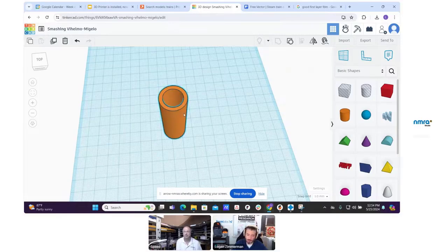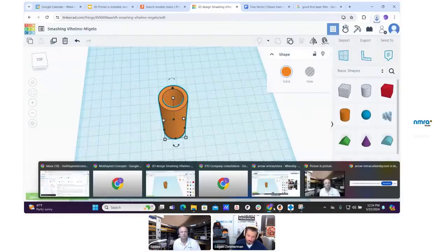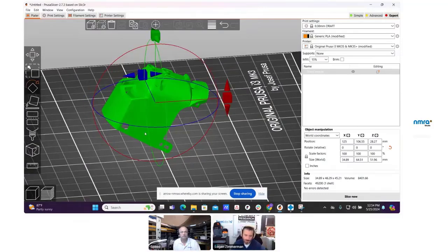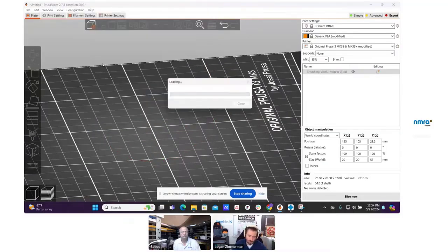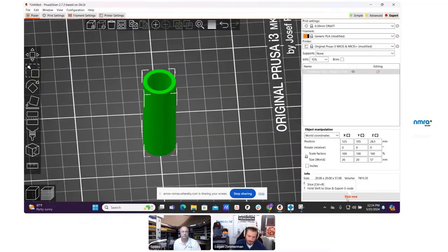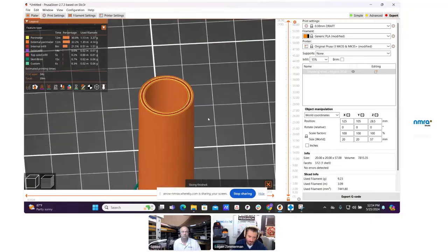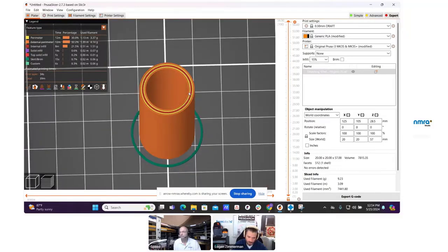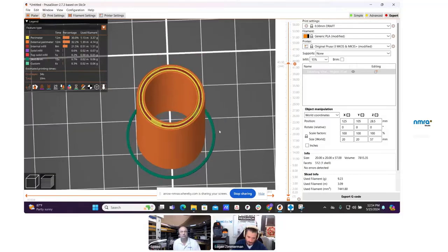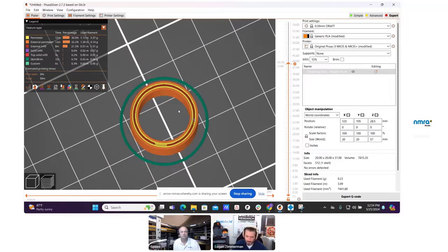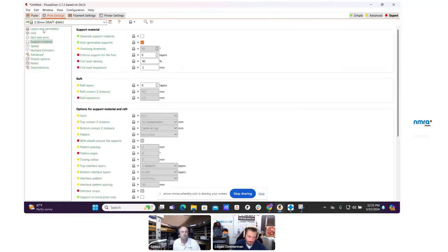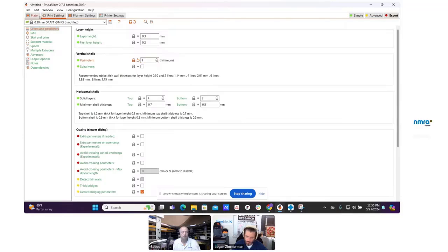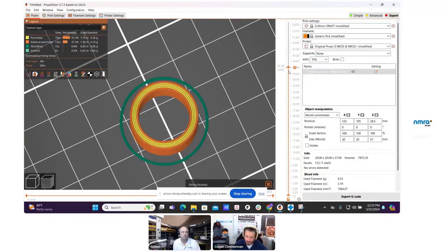Yes, because if I export this, sorry, I'm taking you guys on a journey. We're going to open this. Now when I slice this, you'll see you have 2 layers of perimeters. There's still infill, and you can see it's still hollow, but if this was solid, that infill would go from the second ring all the way across. But because I added that hollowed out area, you have 2 perimeters. Then if I go into my settings and increase the perimeters and slice, now look, 100% infill.